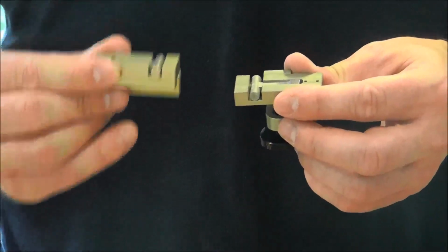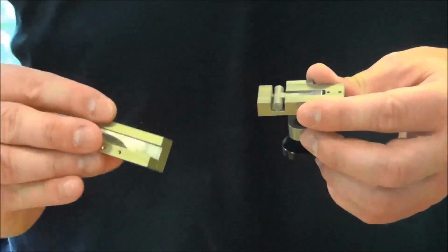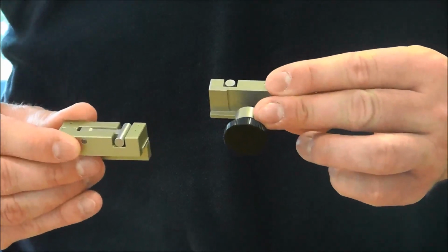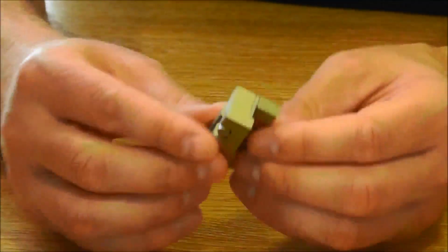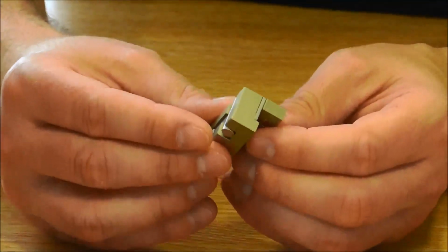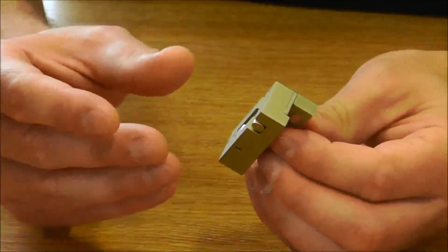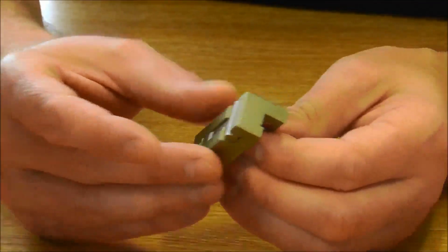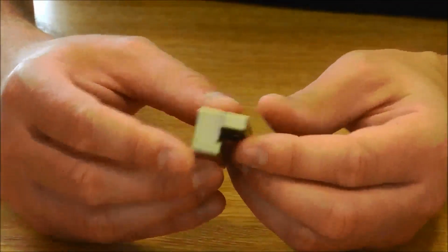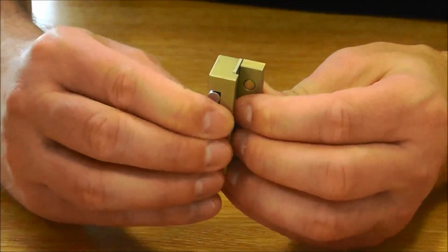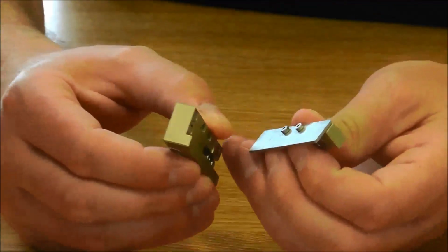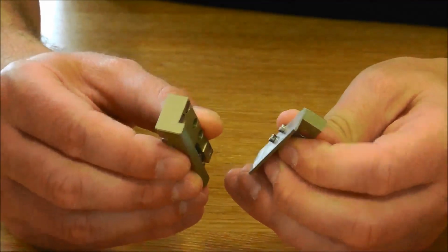There are two different types of friction block as standard. The magnetic type, which can be used on steel-bodied vehicles, and the screw-fix type, which can be used on aluminum-bodied vehicles. The typical range of seal gaps you can measure with a standard block is from around 9mm to 21mm. However, with the magnetic version, you can also add magnetic shims to the block to increase that range further. Another feature of the magnetic block is that it has a removable fixture on the bottom, meaning it's also suitable for 90-degree seal gap measurements, such as on the tailgate.